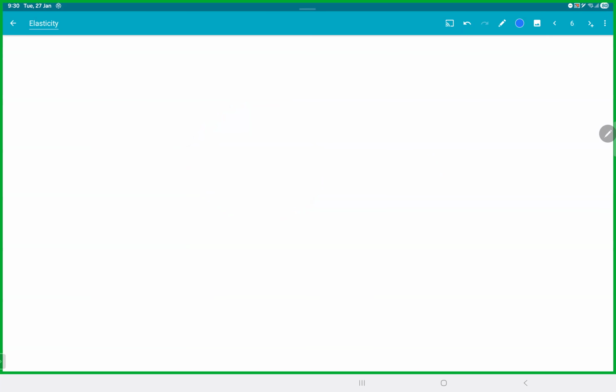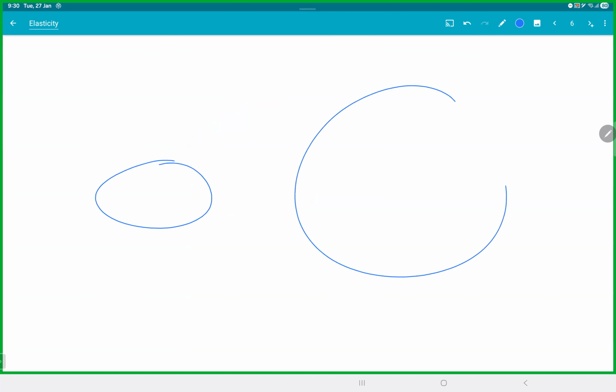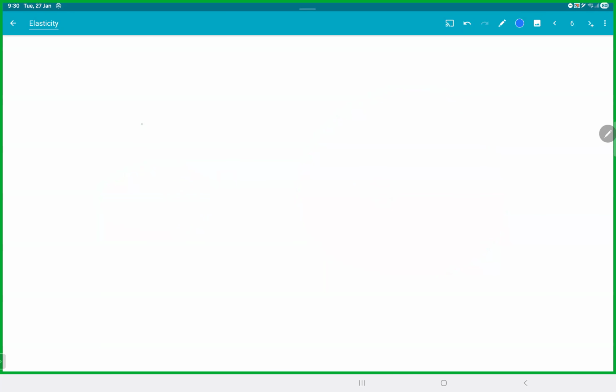You actually do this. That is, if the rat is the same size as an elephant, then you can compare the bones, right? Directly comparing, obviously the elephant's bone is definitely stronger than a rat's, but that's a wrong comparison. So what we do is take the rat's bone and measure the area. Let's say it is 1 centimeter square, and then we apply some force slowly and see at what point it will crack. For example, let's say it can withstand 100 newtons in 1 centimeter square before it cracks. So that comes out to 100, and 1 centimeter square is 10 power minus 4 meter square. That's around 10 power 6 newton per meter square.